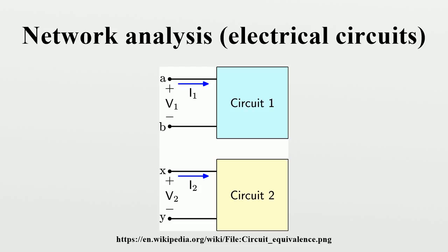Image analysis. Transmission lines and certain types of filter design use the image method to determine the transfer parameters. In this method, the behavior of an infinitely long cascade-connected chain of identical networks is considered. The input and output impedances and the forward and reverse transmission functions are then calculated for this infinitely long chain. Although the theoretical values so obtained can never be exactly realized in practice, in many cases they serve as a very good approximation for the behavior of a finite chain as long as it is not too short.